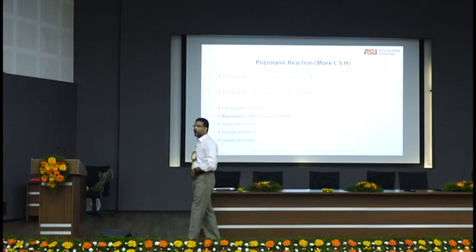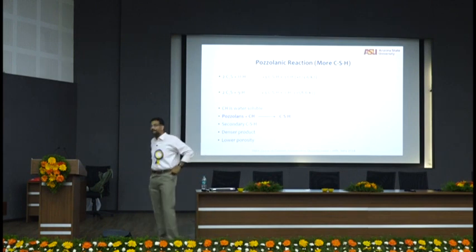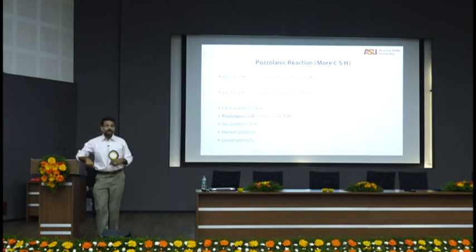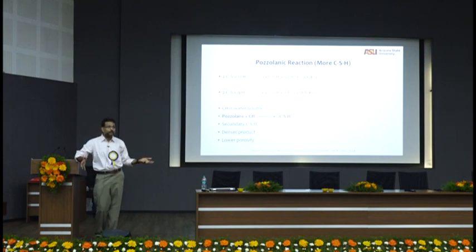So when people say, oh, when you have fly ash, the pH of the concrete goes down because my calcium hydroxide is low, therefore it will corrode. Nonsense. Okay, your pH will go down. Yes, your pH of your concrete will go down. pH will go down from what to what? I'm not going to take the pH down from 12.6 to 9. I'm going to take the pH down from 12.6 to 11.6. But more importantly, you have got a lot of space filled that you won't have ingress of ions into the concrete anymore. Why are you worried about the pH?